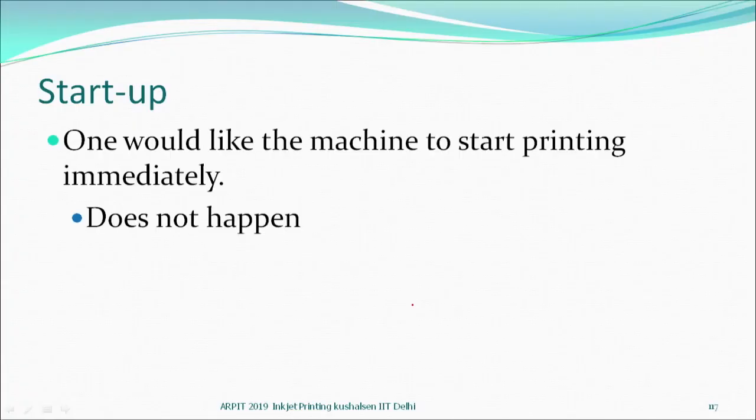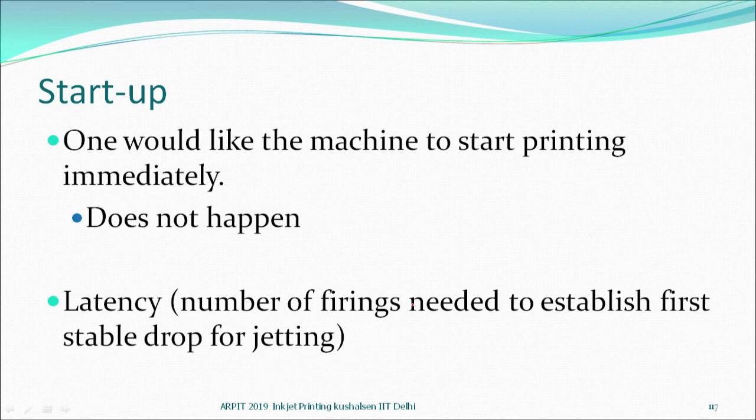At startup, one would like the machine to start printing the moment you push the button. It does not happen. There is something called latency. Latency is the number of firings needed to establish the first stable drop. So, if you have not used the machine, which people should not do, then you may have to stop the machine. You will probably have to clean things, make sure that no deposits are there, but still it will take some time. That is called the latency.